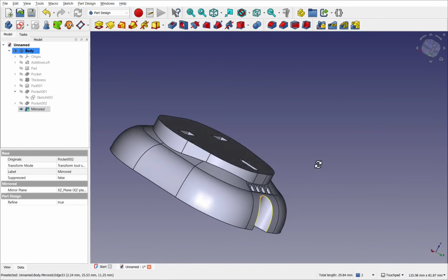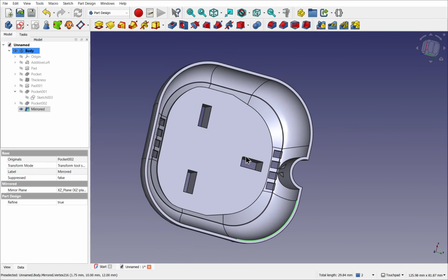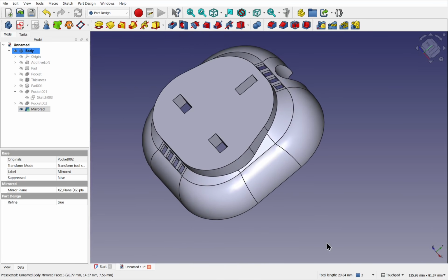We've now completed the project for one side of the enclosure. We learned how to use the thickness tool and also combine multiple operations using additive lofts, pads, pockets, and also the taper option. We've also revisited the mirror. In our next lesson, we'll learn about multi-body modeling and also revisit this project to add additional features to it, such as the lid. With this area, we'll learn about substrate binders and multi-body Boolean operations.